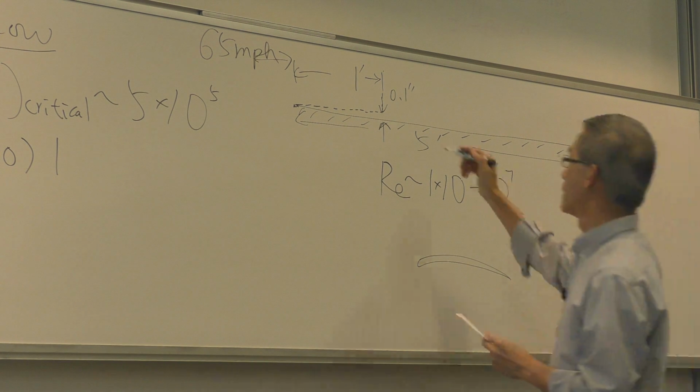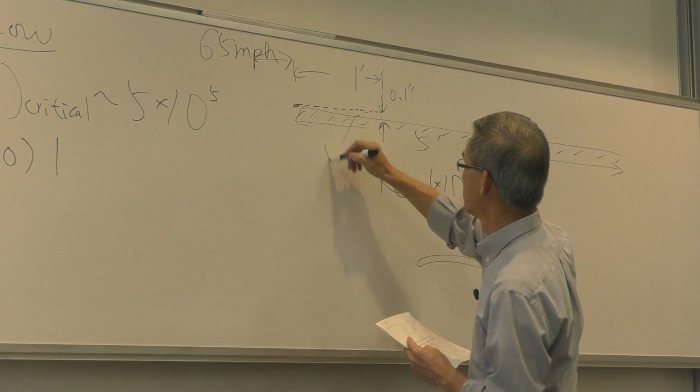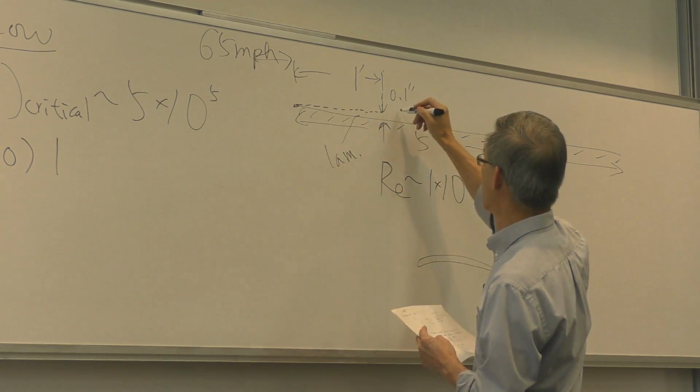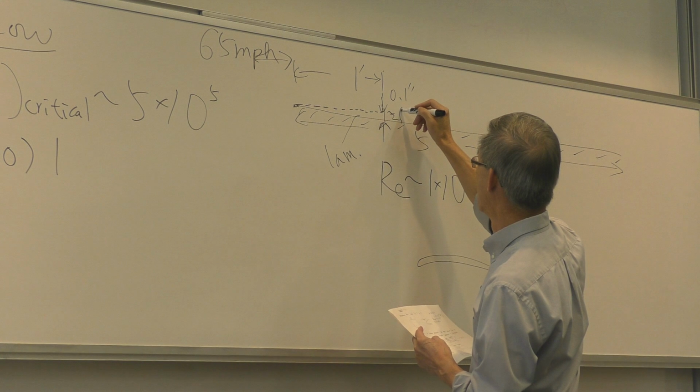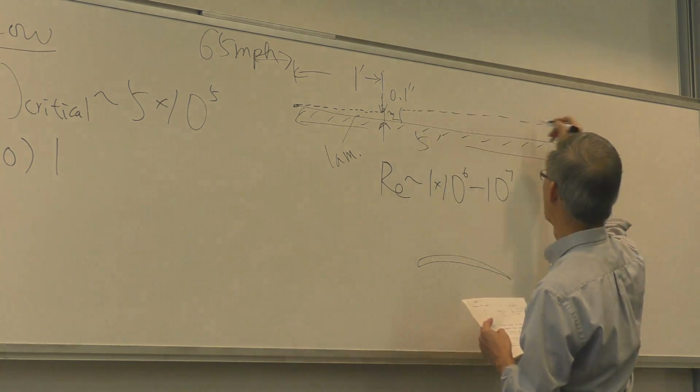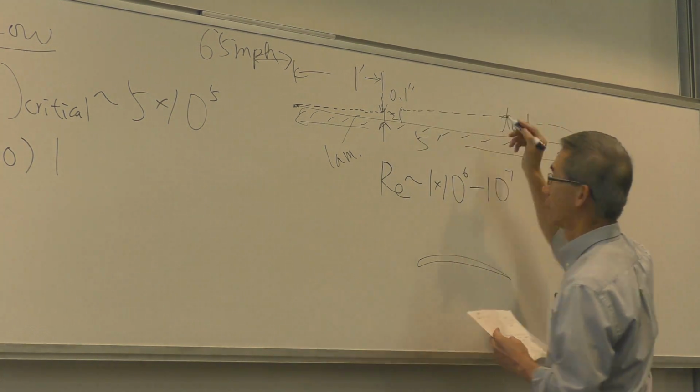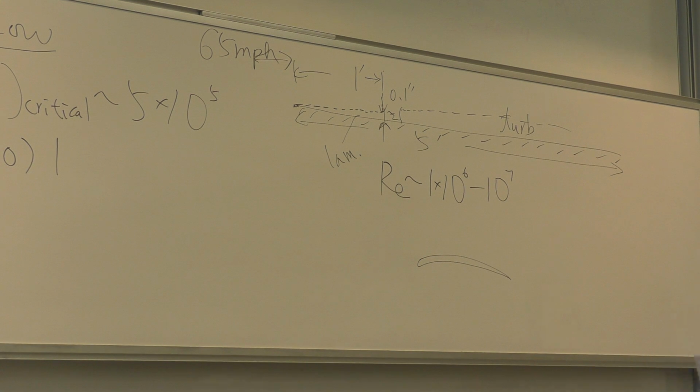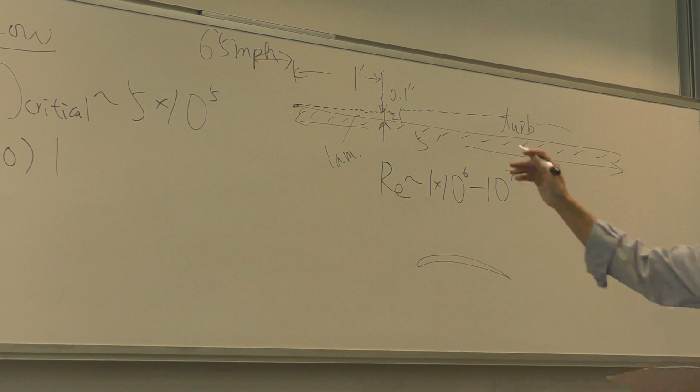And beyond that, the boundary layer becomes turbulent, so this region is laminar. And then there's a transition region, and then beyond that, you have what is called a turbulent boundary layer that is very chaotic, unsteady. The air molecules, you can visualize them as dancing, doing somersaults, talking to each other, mixing, whereas the laminar is very well-behaved layers.